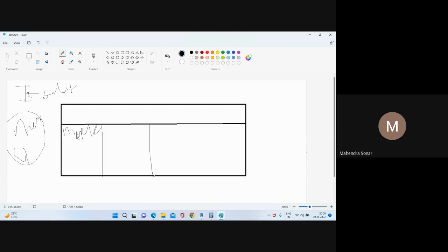Then you can add here type, which type means this I section, column or beam, whatever the name. Okay, suppose this is 250 UC or whatever. So this name appears here. Okay, so you need to go as a type name. Then after that you can add here description. So we have given some fields. So we have added the column, right, and beams. Okay, so those things will come here. So I will explain how they come.